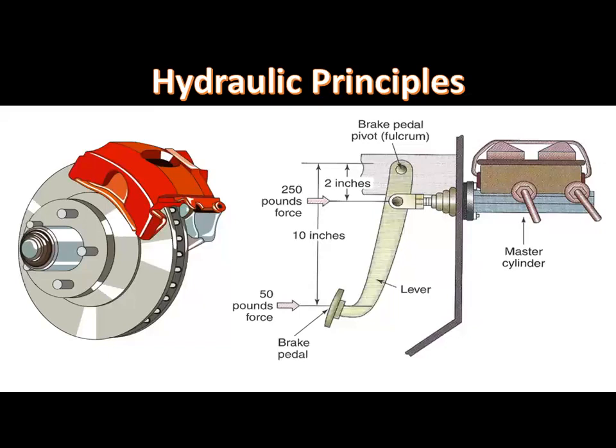Brake system principles that must be understood include the following. If the master cylinder piston and bore size are decreased, the pressure exerted by the master cylinder increases for a given pressure on the brake pedal. If the master cylinder piston and bore size are increased, the pressure exerted by the master cylinder decreases for a given pressure on the brake pedal.